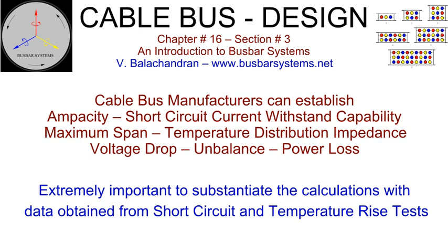Short time current withstand capability. Equivalent resistance per phase considering the temperature distribution. Equivalent inductance per phase considering the spacing and phase distribution. Short circuit forces withstand capability to arrive at the span. Voltage drop at rated current and envisaged power factor. Power loss at rated current.